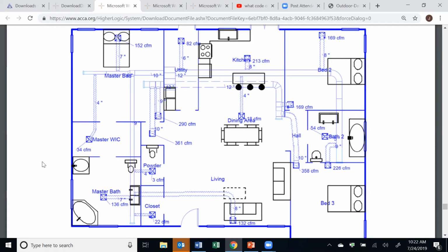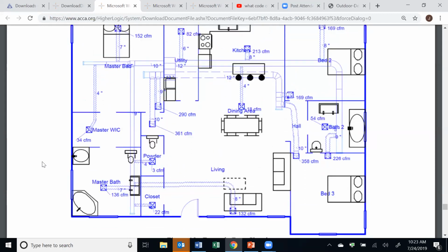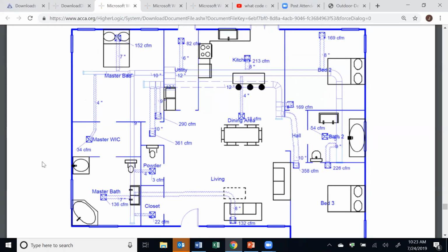So if you look at a duct run and it's marked as an 8-inch, and you look at the CFM and the friction rate, and that's supposed to be a 7-inch duct, well, have that conversation, because if you get a drawing like this that was produced by software, then it's entirely possible that that is supposed to be an 8-inch duct, not a 7-inch duct. Let me see. There was one other point. So that's at the plan review stage.